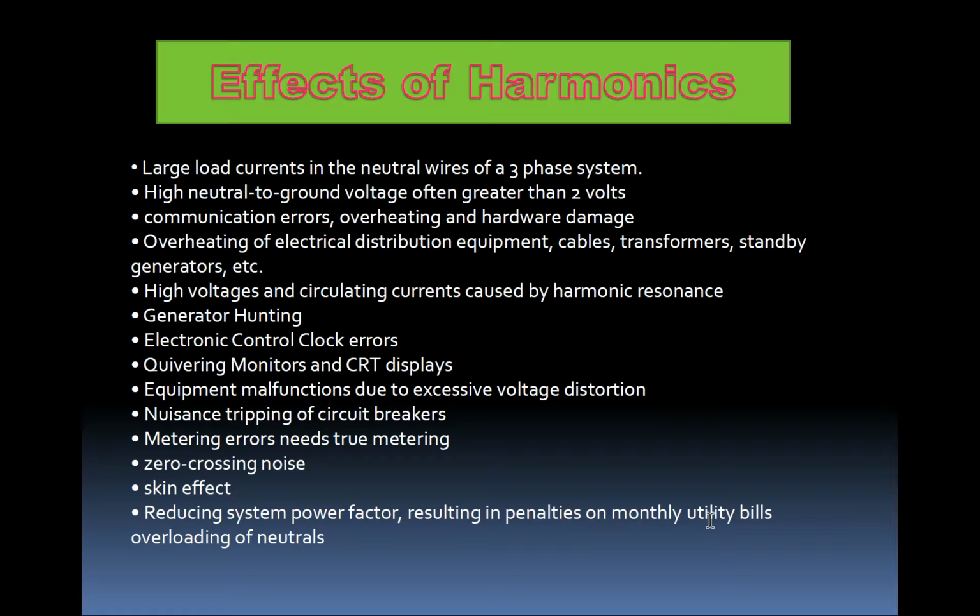That's why certain power utilities do thermal graphic monitoring. Okay, because harmonics is something that we cannot see. We have to measure, we have to monitor using Fluke devices, equipment.